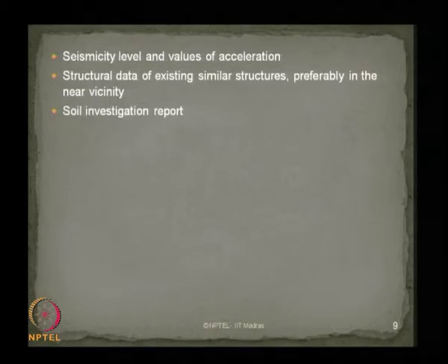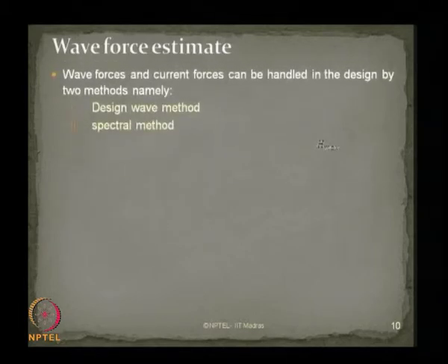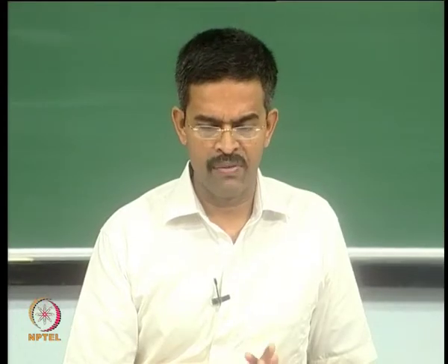To fix up the foundation type, the foundation depth, etc., one should require a detailed soil investigation report of a specific site. Once I have defined the form for a specific offshore structure, once I have chosen the site, once I have the oceanographic, hydrographic data specific to the site, then I am interested to find out what are the wave forces coming on the members in the offshore structure designed and located at this specific site.